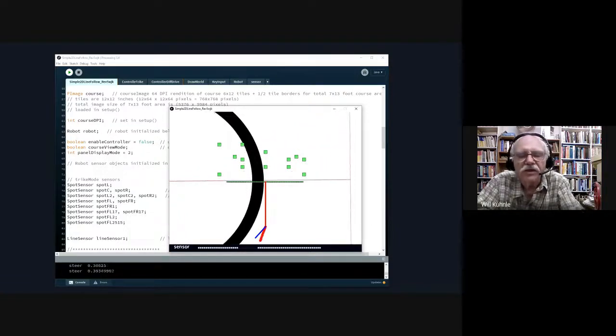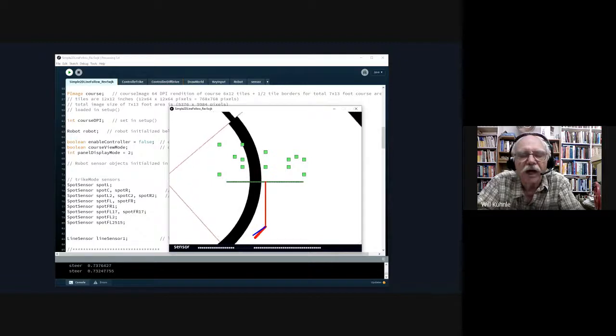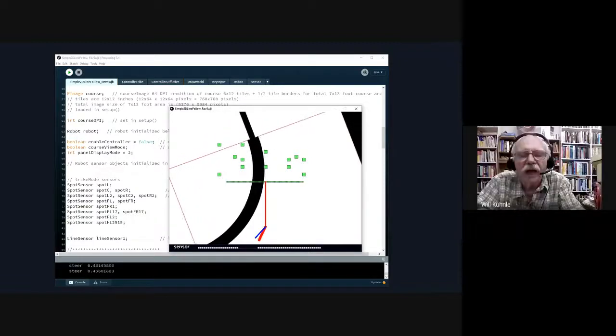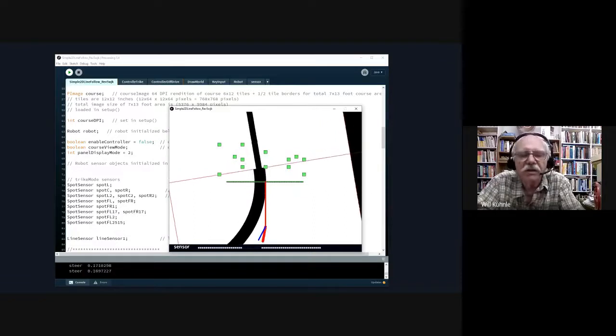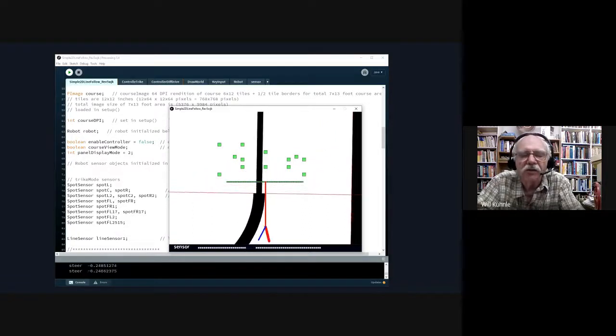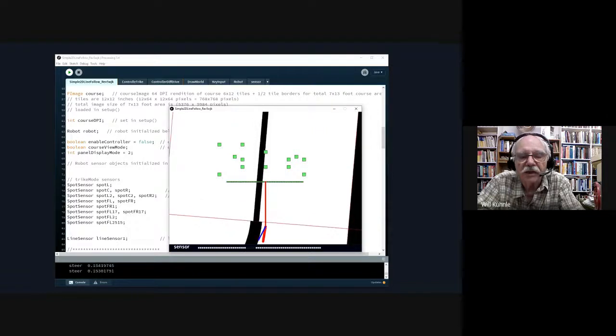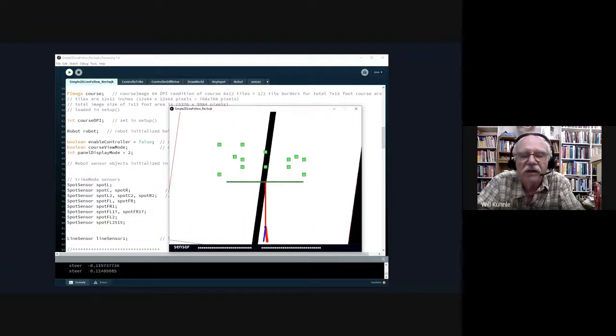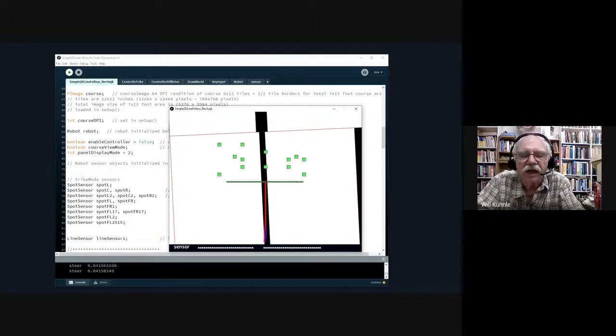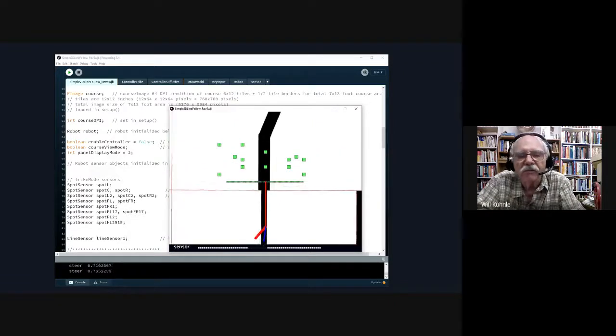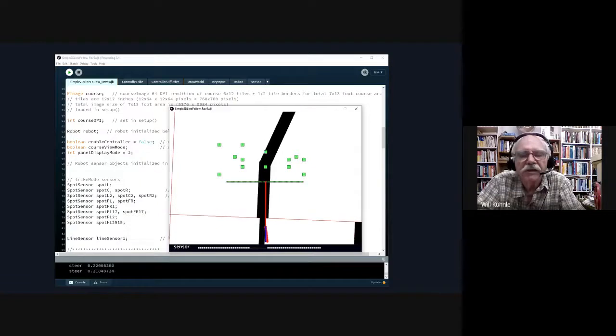You'll notice that the sensor is almost always perpendicular to the line. That's the reason I'm putting my sensor back between the wheels. By the way, it is exactly on the line, I mean, on the centers. And you'll notice while it's kind of nervous, it is following the line. It takes about 6 or 8 inches of travel to settle out. I haven't been able to go the full distance yet, but I'm making progress on that.